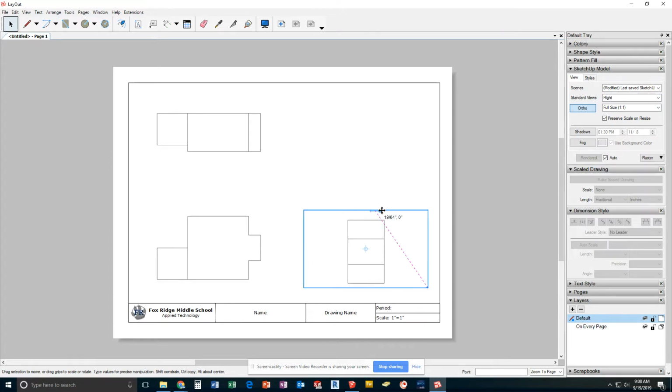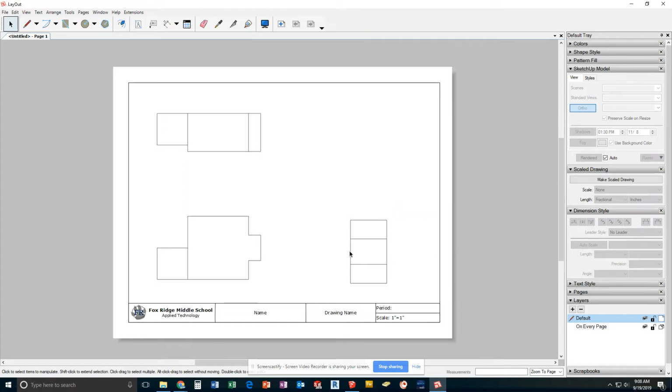And they are set up in a way that if I was to grab this block looking at it from the front and turn it to the right, this is what I would see. If I grab this block and turned it to look at the top, this is exactly what I should see, and everything's lined up and square. Do not rush this. Setting up the views is something that you get points for. It's about 20% of the grade.